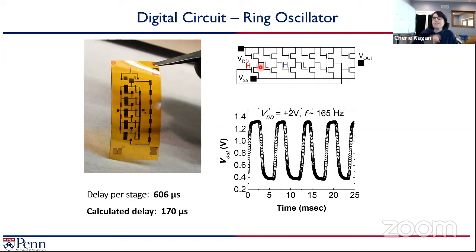And so what happens is that by choosing an odd number of inverters, you get this ringing behavior because you're alternating between whether the signal out is high and low. And that's what you see here. It's high, it's low, it's high, it's low. And that's how a ring oscillator works. And the faster this time scale is, it gives you a way to measure how fast your transistors are that are contributing to your circuit. So you might notice that this says milliseconds, which is kind of slow. So what was the important characteristic?